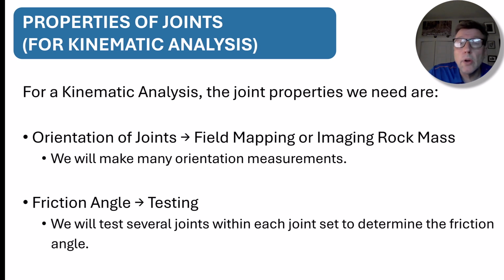Okay? We also need to obtain the friction angle. We obtain the friction angle through testing, and we're going to test several joints within each joint set to determine an average friction angle.